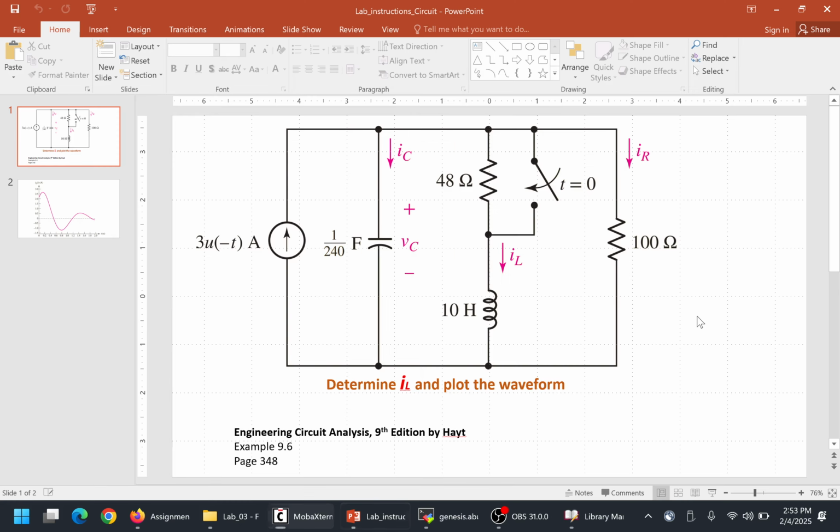All right, if not, then I'll choose. So we have all the currents going down, and for the source we have a current going up. So I'll choose this current source, we'll choose the down node. For the others, we'll choose the top nodes. Got it? Any question? Wait, can you repeat that? I'm just saying that you see IR, IL, IC, all three are going into the components. So I'll choose the top nodes. For the current source, I'll choose the down node because it will still be into the component, which will be from bottom to top.